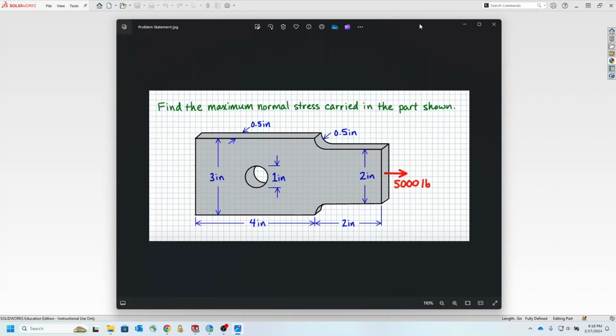So essentially, what you have learned so far about motion analysis was SolidWorks treating every part of the assembly as a rigid part. And the whole objective of the motion analysis was to have some actuator, some motion in some parts of the assembly, and we were interested in the response of other parts, for example rotation of the crankshaft and then a motion of the piston as a response to that actuation.